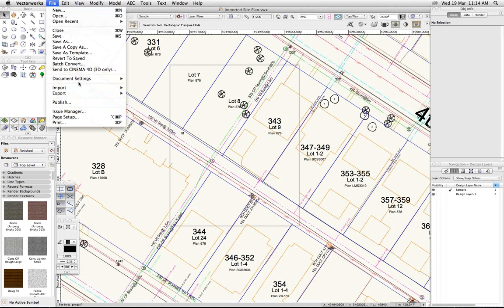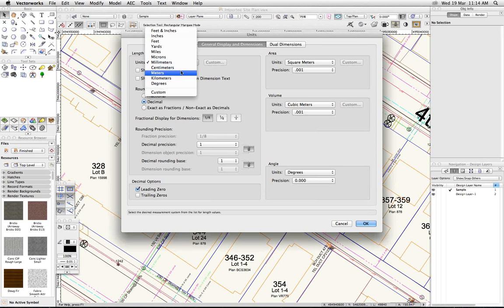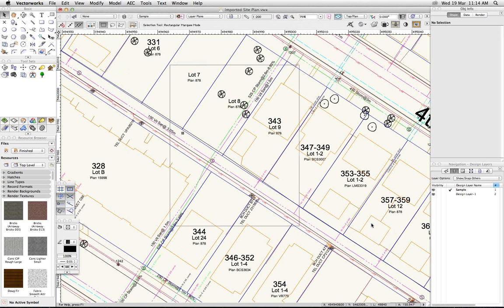and let's just take a look at the way we're set up right now. Meters would make the numbers a little less massive. And what we want to do is that in all files in the project, we now want to work with these coordinates somewhere close to our center, our internal origin, our 0,0 according to that page.